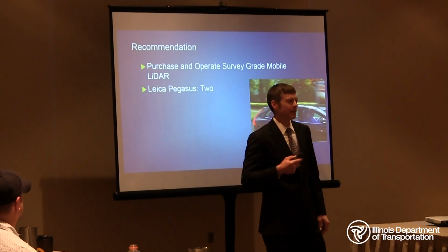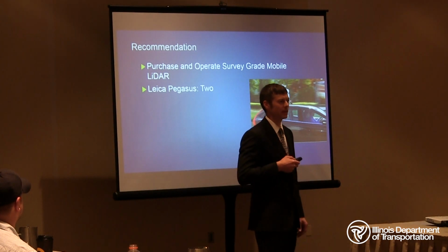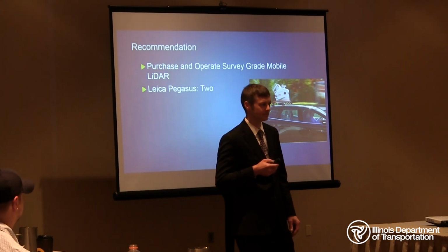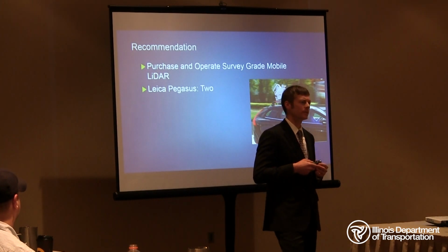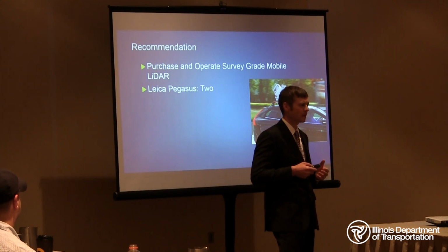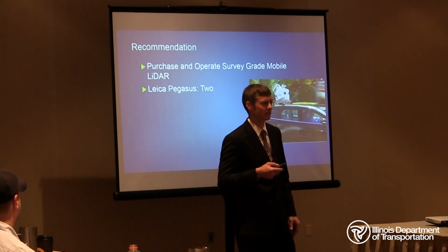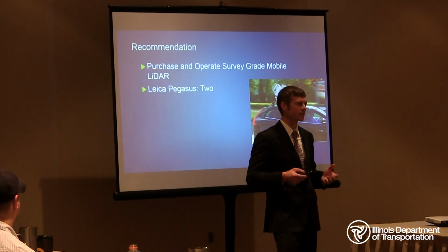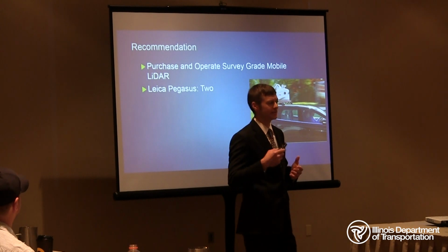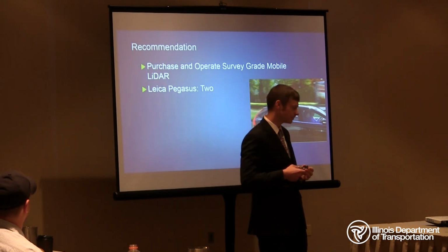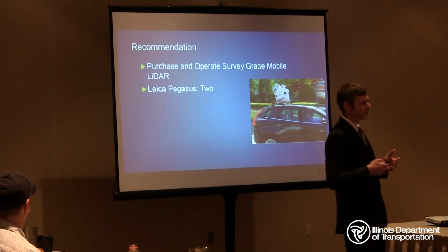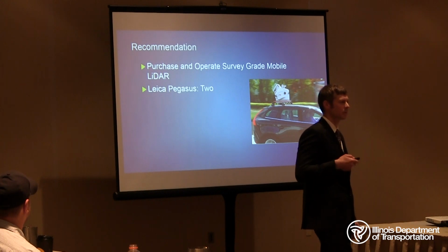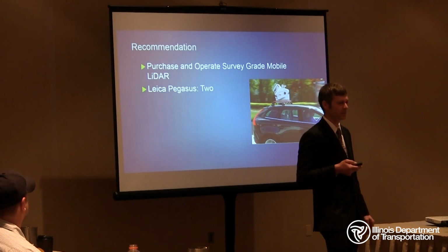We do recommend the Leica Pegasus 2 unit. We determined that it had the best range accuracy and IMU of all comparable top-of-the-line instruments. Leica also offers local training and support, and their units are serviced domestically. Contrary to that, Riegl units are serviced in Austria, and that can create downtimes of up to 2.5 months. And we do know that District 3 consultants completed mobile LIDAR projects with the Leica Pegasus unit and were able to achieve those survey-grade accuracies that we're looking for.